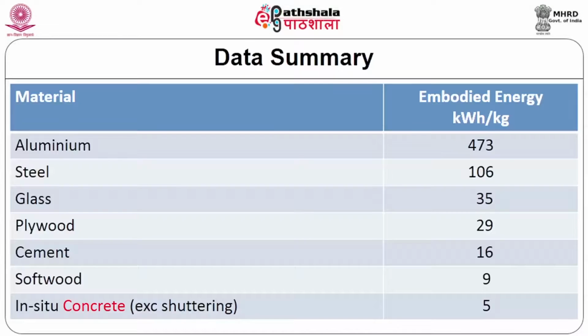Then in comparison of the material or assembly, if you have elevated timber floors, the entire floor, the megajoules per square meter would be lower compared to a concrete one, especially if it is a precast and a concrete slab on ground, it is pretty much on the same line. Roofs, timber roofs initially with the plasterboard without any insulation or anything, compared to concrete or tiles and everything, are lesser.